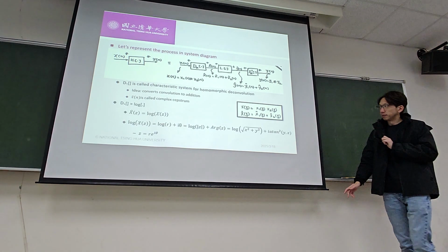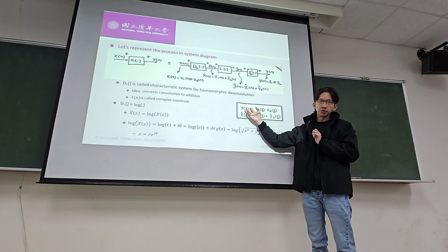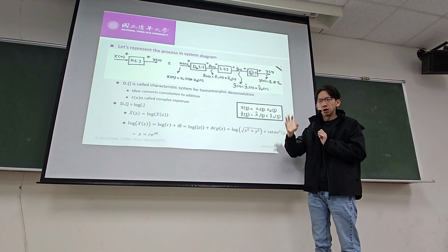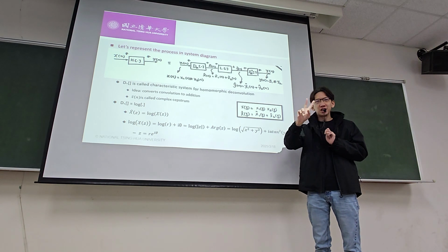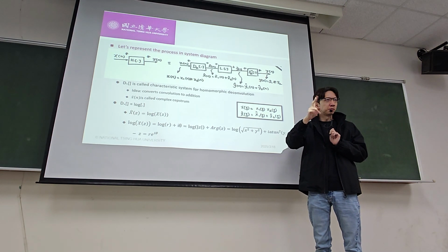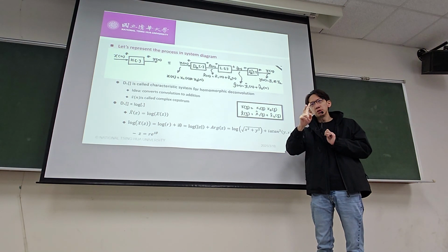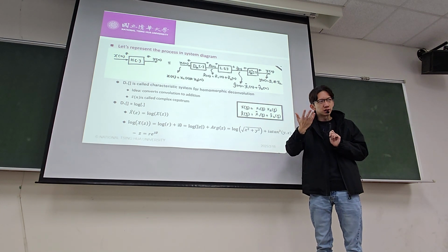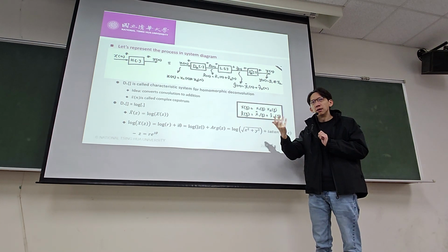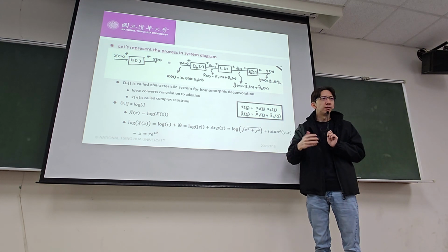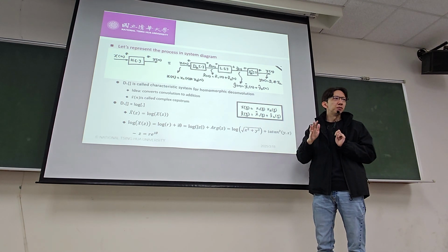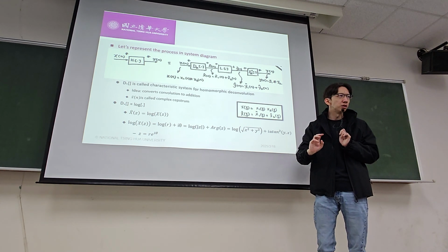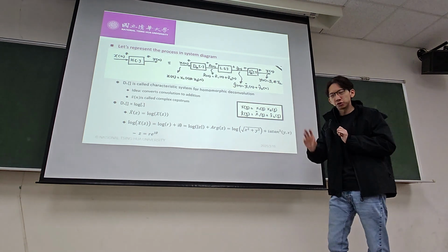So the idea is very simple. Take some Z transform or Fourier transform, X(z) = X1(z) X2(z). Please note in this lecture we interchange Fourier transform and Z transform quite a bit. The Z transform is usually utilized more for analyzing discrete systems and discrete signals, but they are essentially equivalent for the sake of this purpose. Take z = e^(j omega), then these two things are equal to each other, so we utilize them sort of interchangeably.